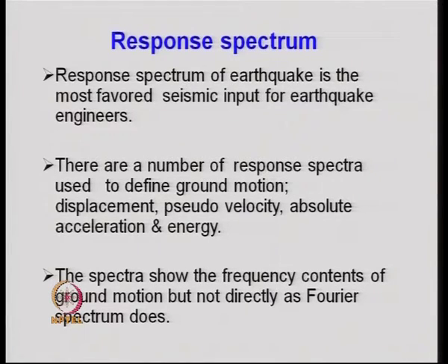Response spectrum of earthquake is the most favored seismic input for earthquake engineers. There are a number of response spectra used to define ground motion: displacement, pseudo velocity, absolute acceleration and energy. One can obtain the response spectrum for each one of these parameters. The spectra show the frequency contents of ground motion, but not directly as the Fourier spectrum does.